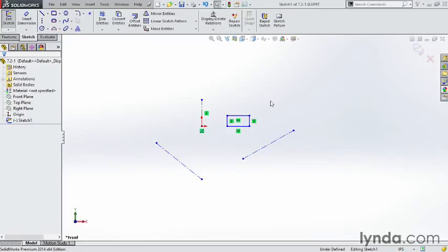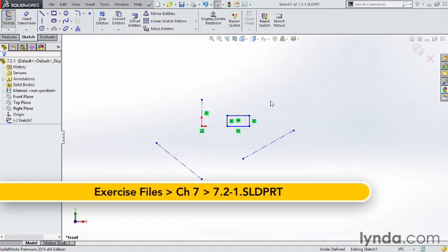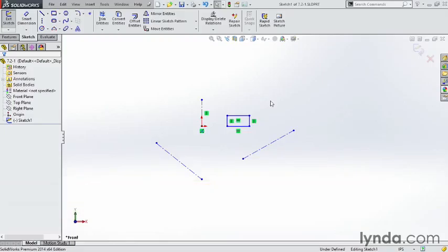Much like the extrude command, the revolve feature creates geometry from a sketch. However, the revolve requires one more ingredient, the axis of rotation. Once you have a sketch, the next element is a center line, axis, or internal line of the sketch.